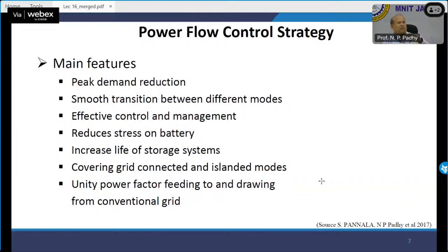not forcing the battery to oscillate as and when required in its own way. Otherwise, what will happen? Every time it will fluctuate, because the load keeps on varying. So you give strict commands only at the boundary. If it is below 70, you do it, otherwise don't do it. That means you are restricting the charge-discharge cycle by a factor of 10 to 1 or 2. So the charge-discharge cycles become very, very few compared to a regular cycle if you do not have a control mechanism in place.